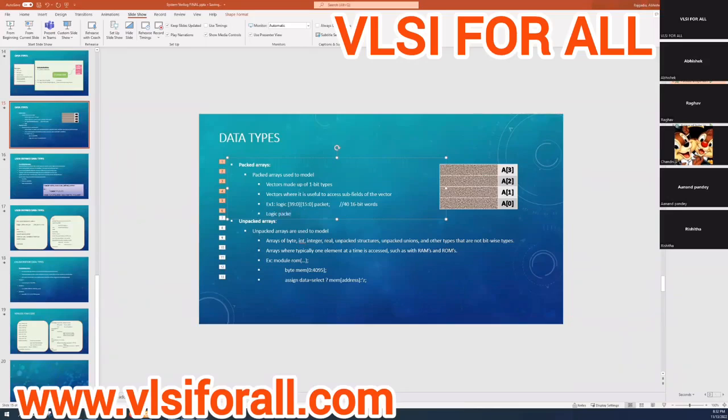It's a good question actually. In terms of accessing, it's always like this. You'll access 15 down to 0. So when you do 15 down to 0, you are accessing all of it. When you access the packed array or the unpacked array, it's in the same way. There's no difference when accessing the packed and the unpacked array. You have to write on the right hand side.